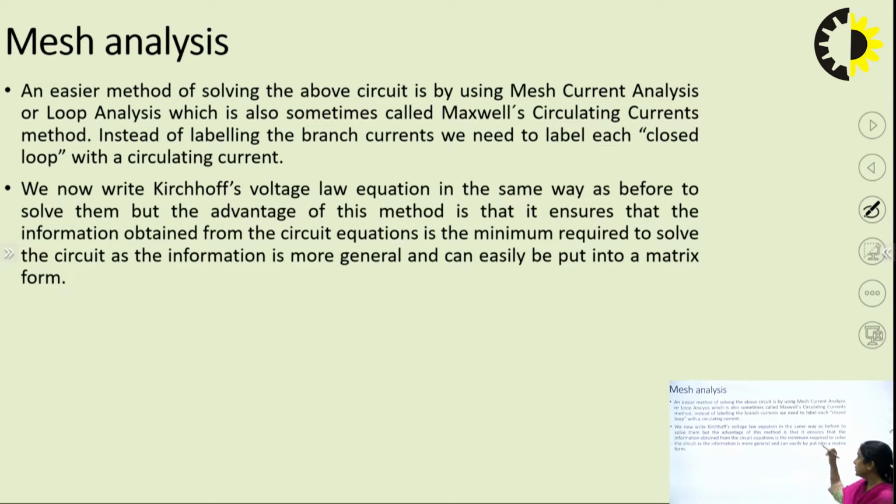So instead of labeling the branch current, the current through each element, we label the current in each mesh, an individual current. After labeling the individual current in each mesh, we write the Kirchhoff's voltage law equation, as we used to do earlier also.